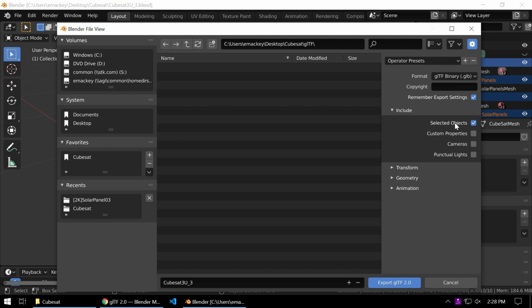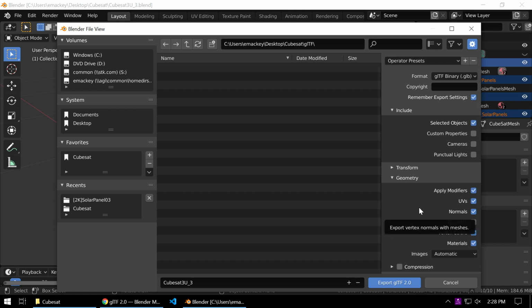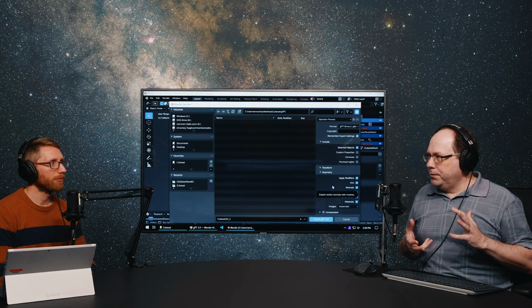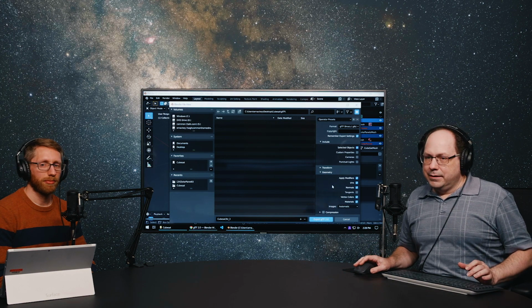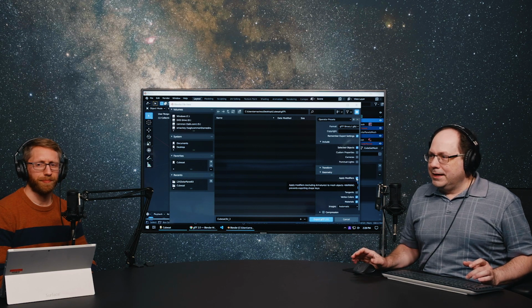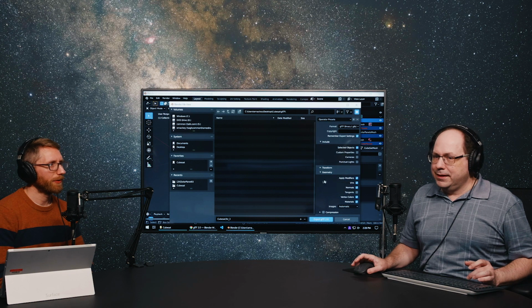I mean, the camera and the light, if they got exported, it's no big deal. But later on, maybe in the next video, I might have baked targets or something. And for this one, I am going to apply modifiers because if you recall in the first video, I did a lot with that auto smooth stuff going on. And there's an implicit edge split modifier that happens that needs to get applied.